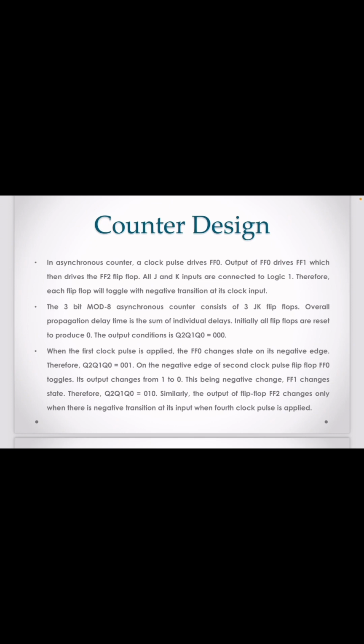Now I will talk about counter design. In an asynchronous counter, a clock pulse drives FF0, the output of FF0 drives FF1, which then drives the FF2 flip-flop. All J and K inputs are connected to logic 1. Therefore, each flip-flop will toggle with a negative transition at its clock input. The 3-bit mod 8 asynchronous counter consists of 3 JK flip-flops overall.